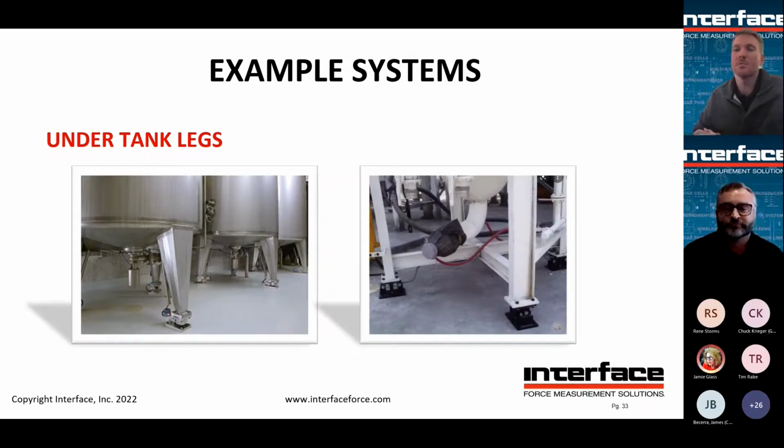Also, consider how the system will be calibrated. And we'll touch on different calibration methods a little bit later, but test weights are always recommended, but substitution methods are very common in the field. If you can get with a tank designer, let them know, hey, it's a good idea to consider how we're going to either hang or attach test weights to this to be able to calibrate it.